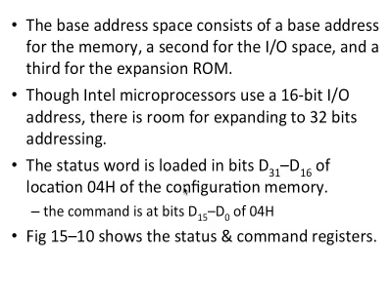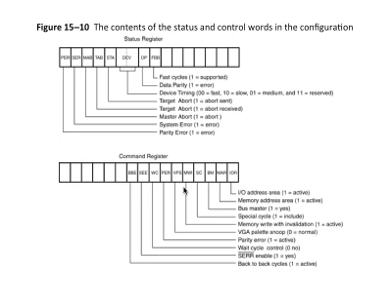The other two words are status and command, which are located in the second double word of the configuration space, and the details are here. I won't go through each of these individual pins, but what you're going to understand is that the PCI device uses these two registers to report the status and also to receive commands from the operating system.